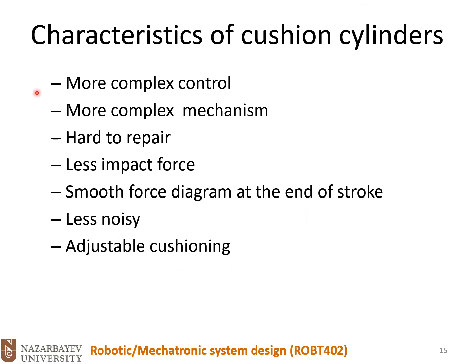What are the characteristics of cushioning cylinders? More complex control, because the acceleration is not constant. More complex mechanism because of the cushioning compared to the regular double acting cylinder. Hard to repair because we have more parts. We have the orifice, we have a set screw, and there is a rod attached to the piston.